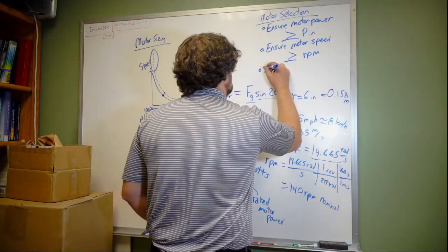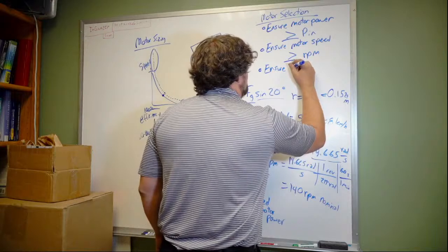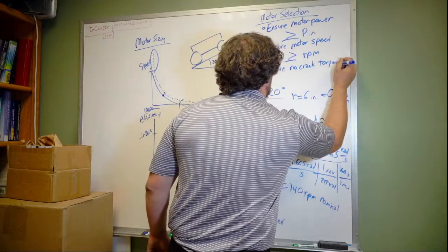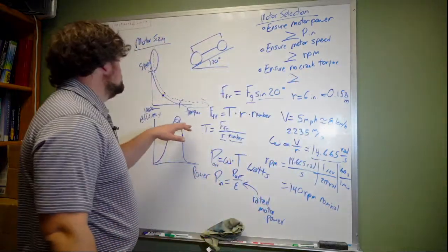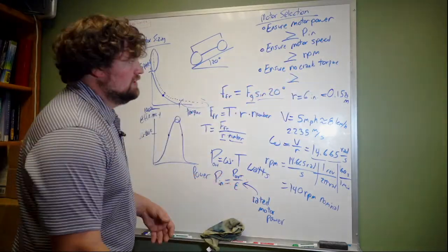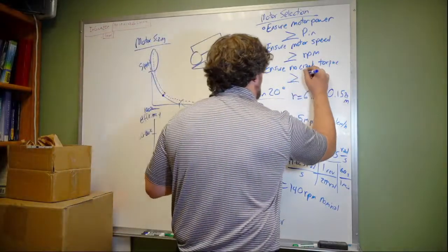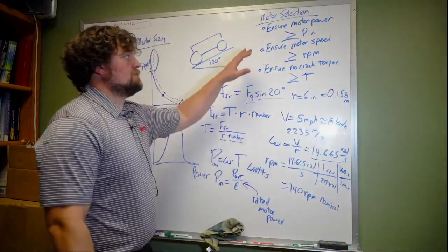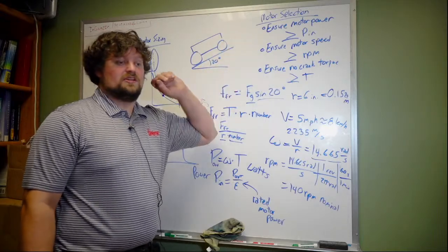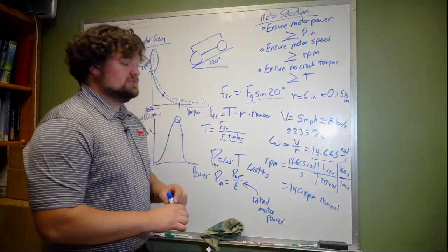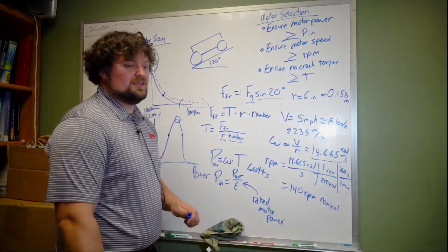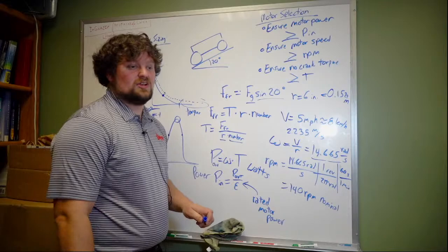Okay, and then the third step is you've got to ensure that your no crank torque has got to be greater than or equal to this torque value that we calculated over here. Now ideally all three of these would be greater, hopefully. But those are the three checks that you need to make. If a motor you select beats all three of those criteria, that is a good motor for your application. Okay? So that's Cale's quick and dirty calculation method for sizing motors for vehicles.